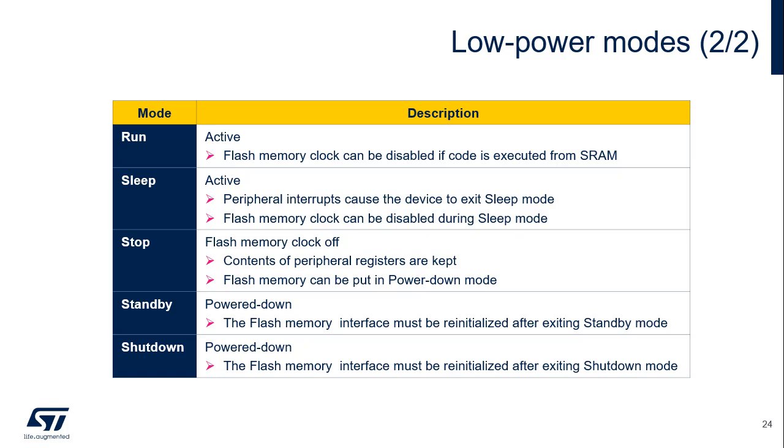In run and sleep modes, only clock gating is supported. In stop mode, the clocks are gated, and flash memory can enter power-down mode. In standby and shutdown modes, the power to the flash memory module is gated for both the flash memory and the controller.